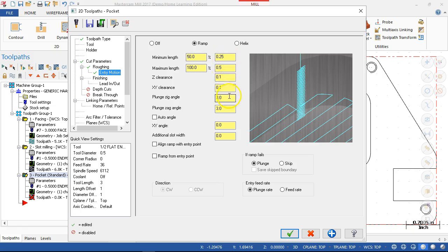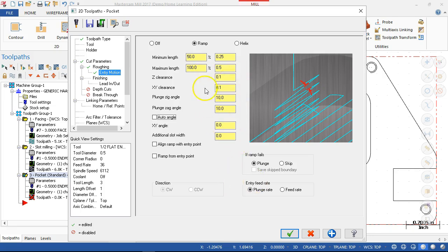And clearances were okay. I still want to be kind of aggressive with the 10. It is kind of annoying the first time you run a 1 degree or a 3 degree and it sits there for 5 minutes going zzz, or the helix at 1 degree is sitting there making 1,000 loops to get to a 1/2" deep, and you're wondering why did that take two minutes to get engaged in the part, right? But that's an observation that you make at the machine and come back and make the adjustment after the fact.